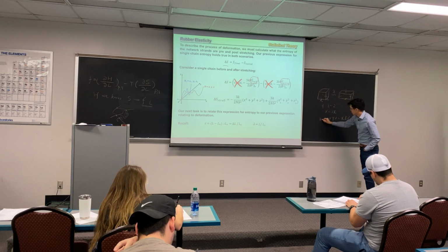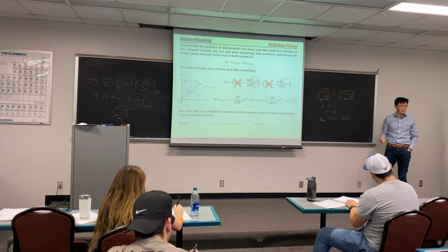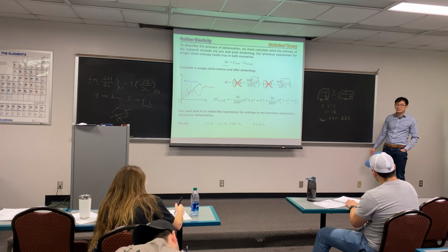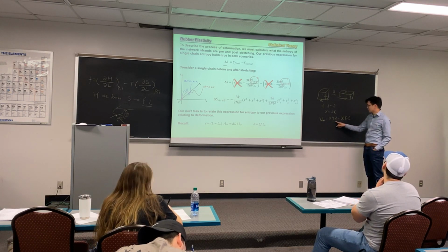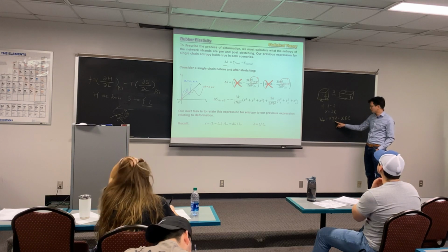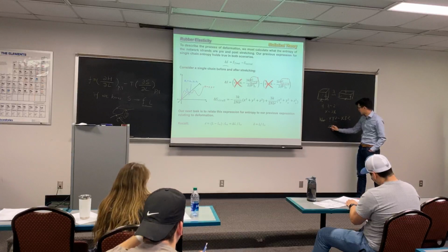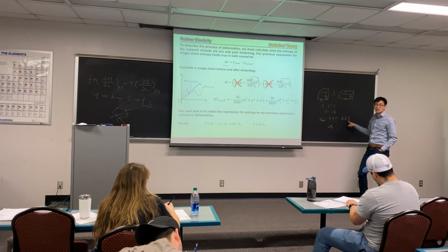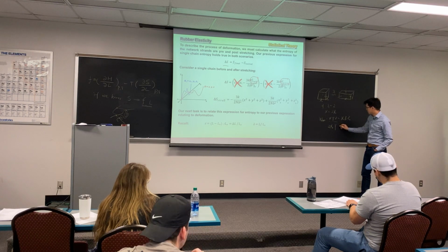This is the volume. There's no volume change before and after stretch. So it will be uniformly deformed in both the y and z directions. We basically know x will be twice of x0. The y and z directions are deformed uniformly, so we can assume y would be equal to z.